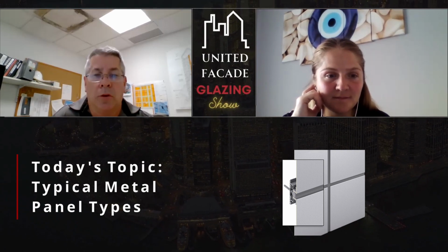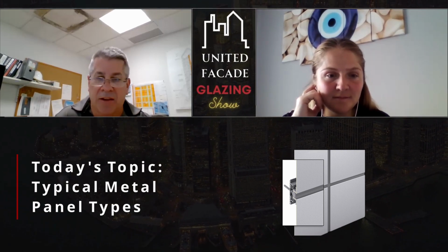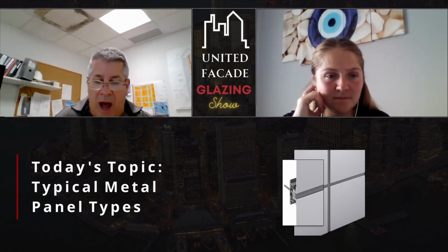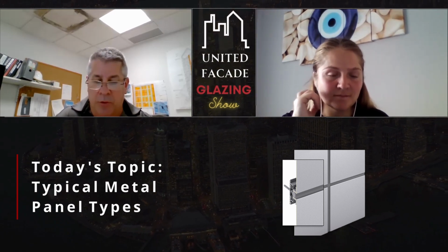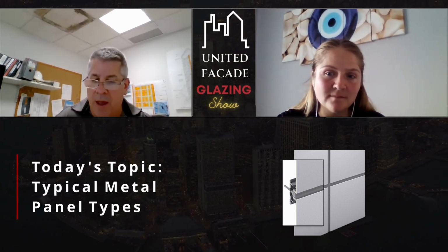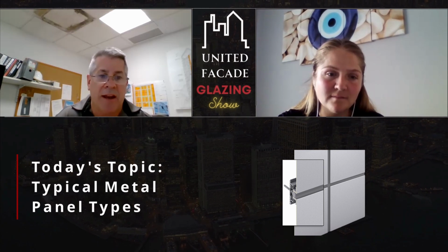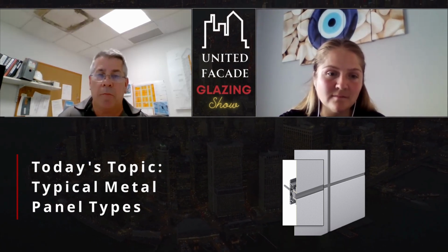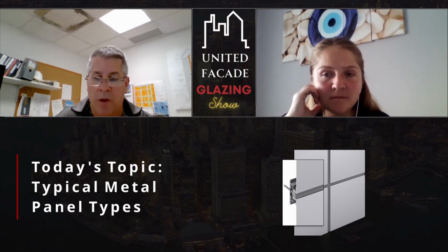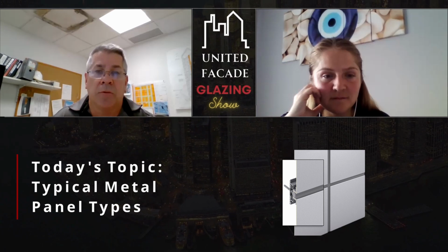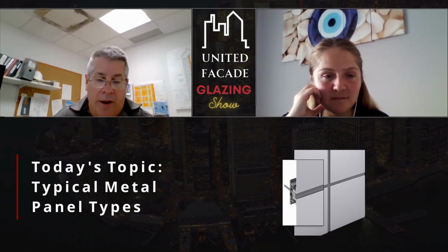Because it's an aluminum skin, you could have it as an anodized material, or you can have it as a painted material. Most common would be the painted material, because each of these main manufacturers are aligned with a paint company, and you could basically make this any color an architect can come up with and get a color code for. They can make the ACM panel that color. So that gives the architect or designer a lot of options as to what color his building will look like.